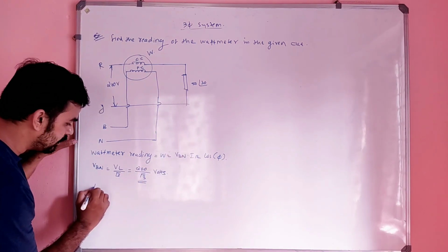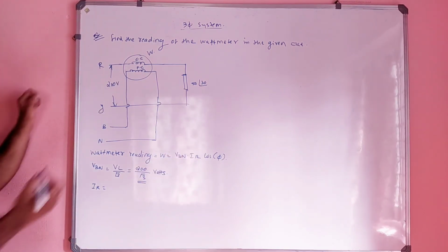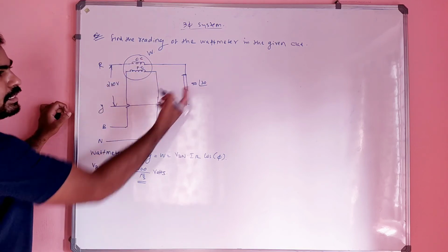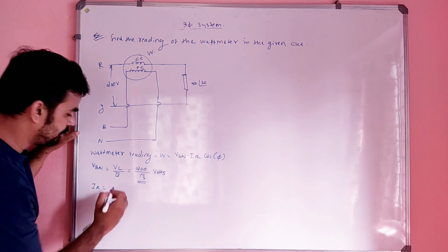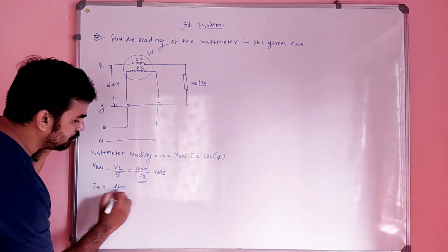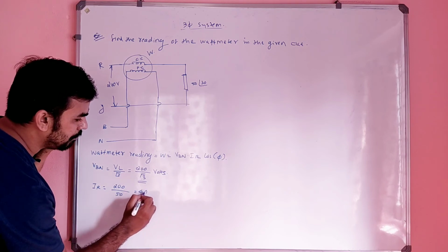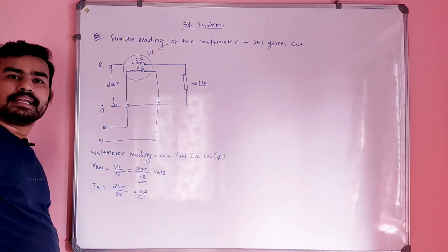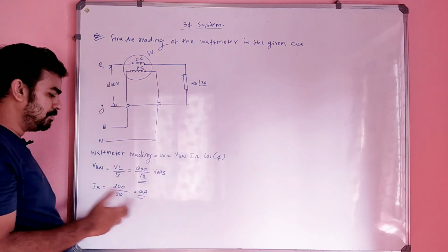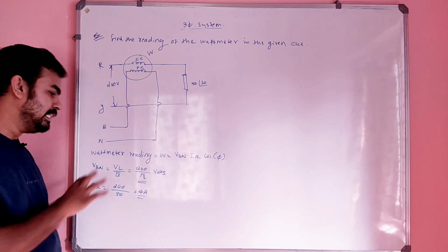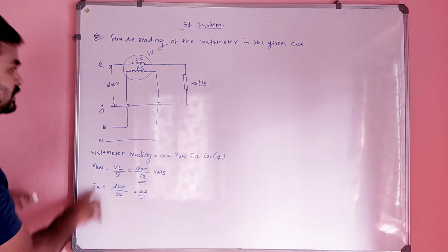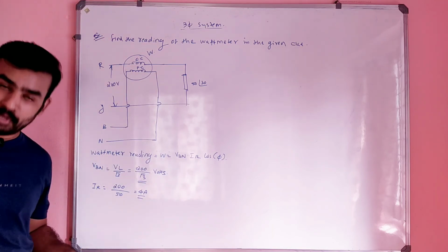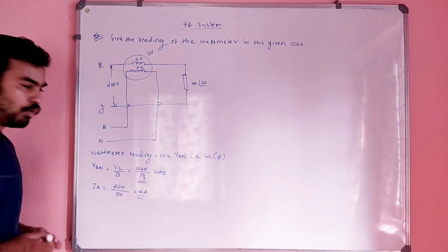And what is the value of IR here? You can easily find it because between these two lines there is a voltage, and the impedance is here also. It is simply 200 divided by 50 angle 30, so 4 ampere. In star connection, the phase and line values of current are the same, so there is no confusion regarding the current. Only the voltage needs care.